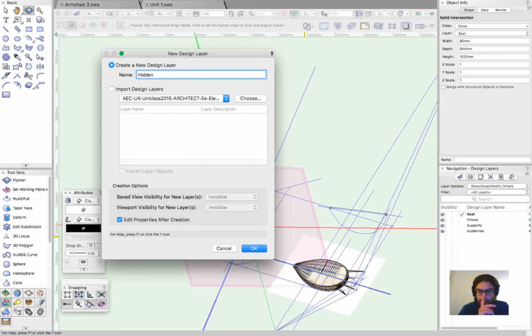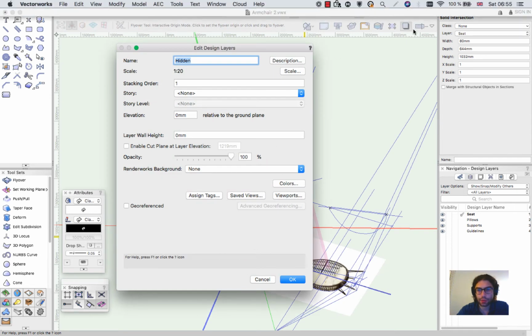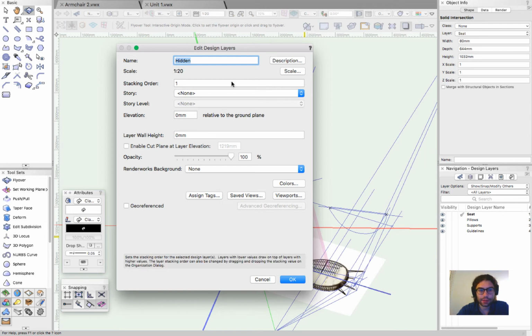So here we have a few workarounds how to hide objects. For example, it could be placed to a hidden layer or hidden class. Also, they could be hidden through data visualization. But now I'd like to keep it simple and don't want to bother you with data visualization. So it will be a class where all the hidden objects will be housed.